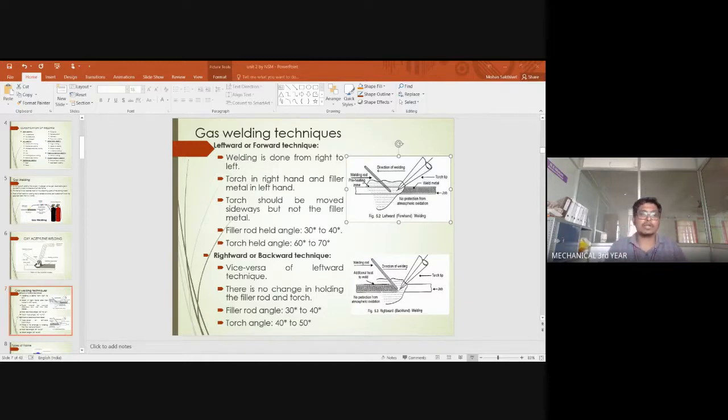Okay, so here we can use both direct and alternating current for electric arc welding, each having its particular application. DC weld supply is usually obtained from generators driven by electric motors, or if no electricity is available, an internal combustion engine can also be used in the arc welding process. For AC welding supply, transformers are predominantly used for almost all arc welding where main electric power supply is available. Wherever electric power supply is available, you can use alternating current, which is predominantly used in all types of arc welding.